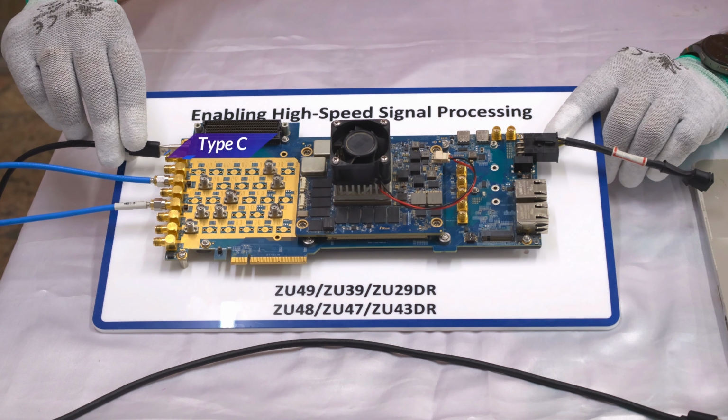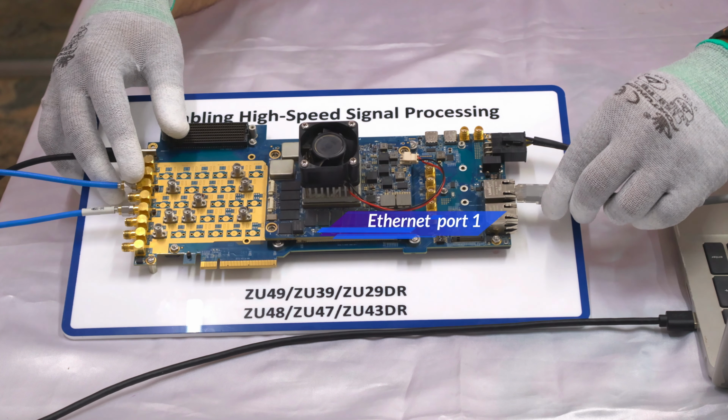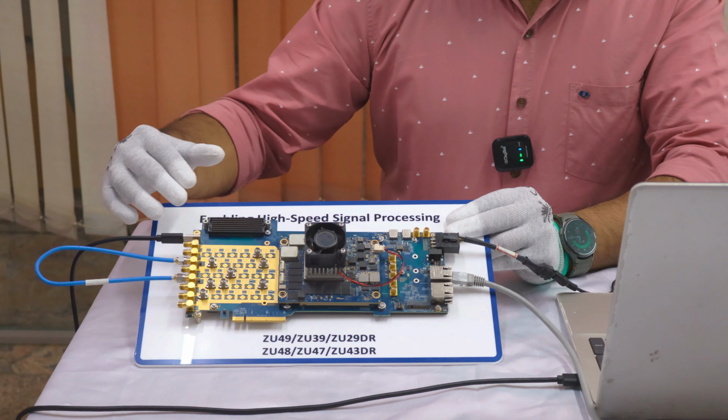We connect the Type-C debug cable into the Type-C port. We connect the Ethernet cable to the ETH1 port. Then we connect the 12V 5A power supply to the power connector. This is the demo setup.